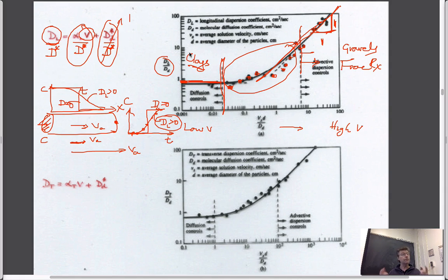And so it's no surprise that if you want to build a landfill, you either line it with clay or build it in clay, because all of a sudden not only are the rates of permeability low, making this velocity very low, the only transport mechanism you have is molecular diffusion. And so in clays, the transport process is completely dominated by diffusion. It's always a very low number, and therefore that's why you put nuclear repositories in low permeability rocks, because this dispersive term is 0, and you only have to worry about diffusive transport.